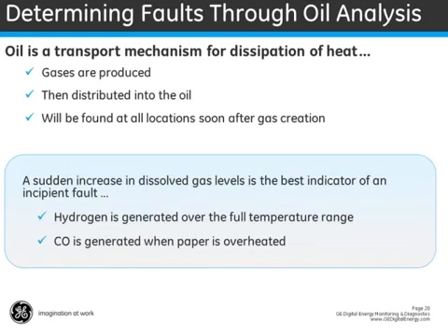Hydrogen is another gas, and it's a little bit unique. It's produced under all fault conditions. This is why we see single or composite gas monitors focused on hydrogen detection in the dissolved gas analysis market. Hydran, a composite gas unit with sensitivity to hydrogen in oil, has been manufactured by GE since the mid-1970s. And in fact, it's a byword for online DGA today. Really, if you have a conversation about online dissolved gas analysis, that conversation is sure to feature Hydran within its context.